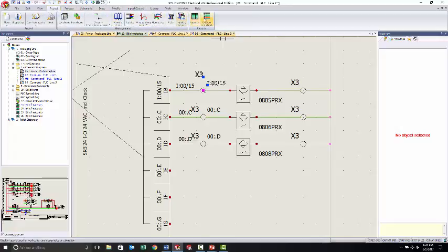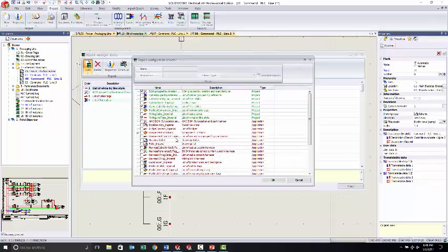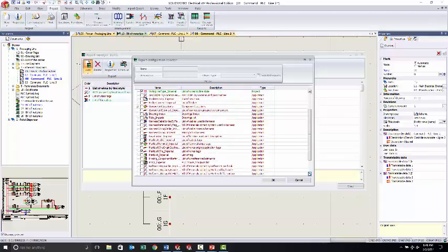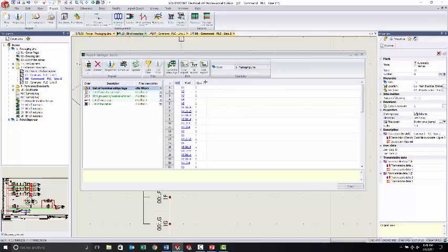Let's see. So under project, under reports, you're talking about a list of terminals. Yeah, just at detail X3, you know. Let's see here. List of terminal strip tags. There's that one. Let's see, what other one do I have? We've done it. You don't have to worry about it. Oh, I can see where that would be. Now you've got a wonderfully chunked out terminal strip detail, which you could then pull the data for terminal strip printing. Yep. Exactly.